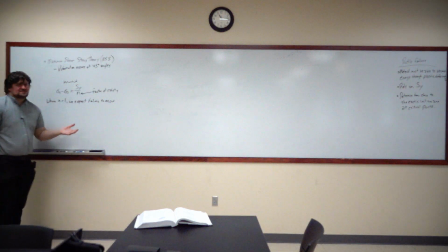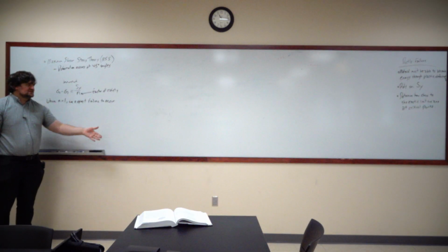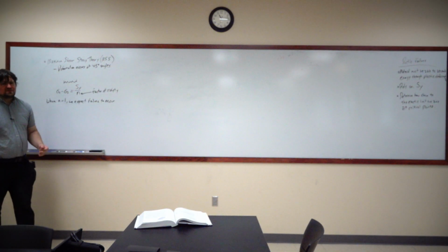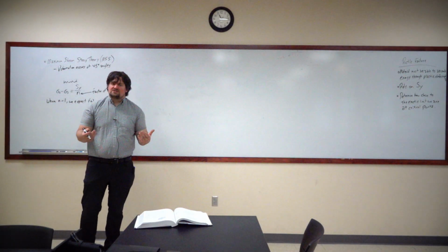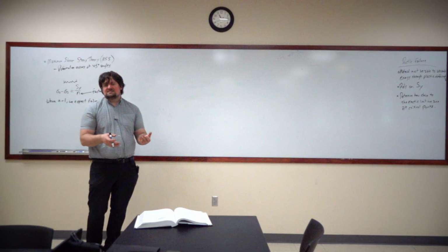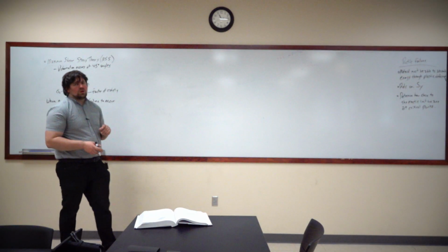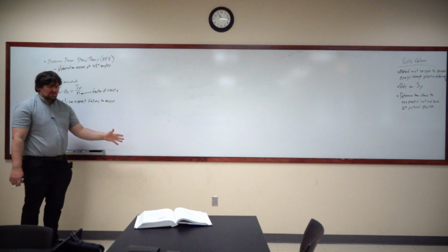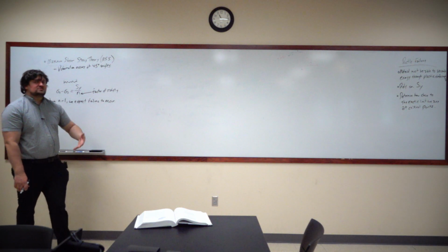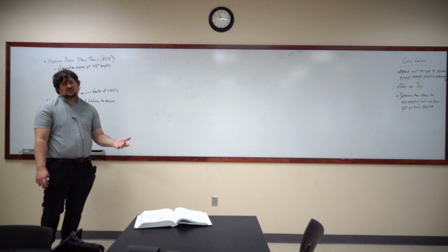Okay, now this ends up being a statistical property because of the way that fracture mechanics works and because of the variability in materials. We aren't going to see every material fail at an exactly specific load. But what we will see is that a lot of materials that are made at the same time and the same processes come from the same material batch. They do tend to fail similarly.